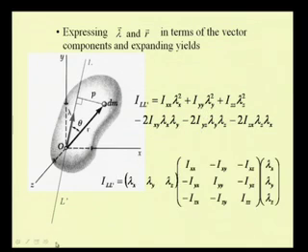So, we can write this again in the tensor notation. This is the inertia tensor, or the inertia values with respect to this x, y, z axis, and this is multiplied by the direction cosines of the axis for which we are interested to know.